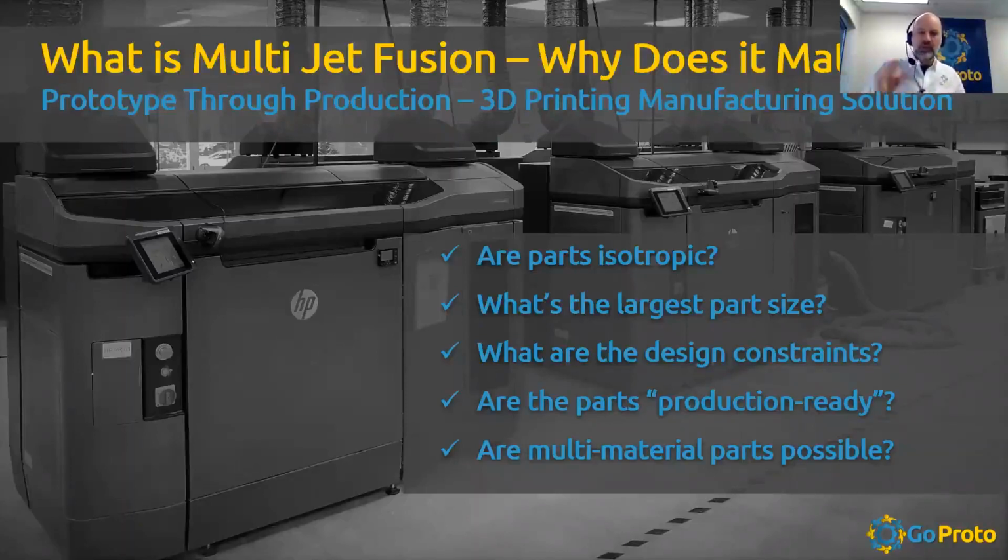But sometimes when we want parts thinner or more cushy, maybe we'll go to foam. Like Rebecca said, the TPA is available in a foamed version. So you can introduce air essentially to create pockets that make it feel softer. Well, with 3D printing, you can vary, again, I'll hold up this little part, you can vary the lattice, you can vary the density of the part to get the cushion that you're looking for. And you can vary it over a part. So that starts to really open up design ideas.